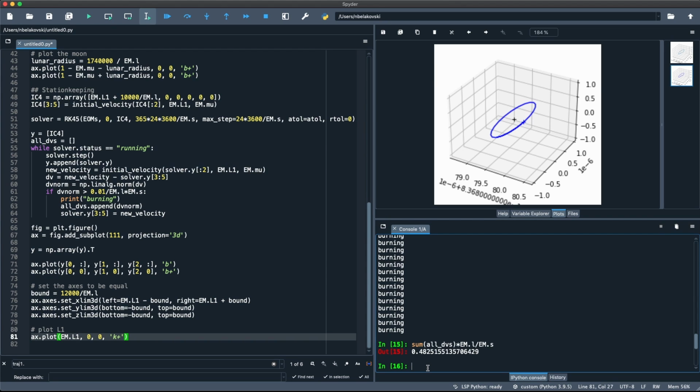The moon's orbit is eccentric, so you're going around in your orbit, and by the time you need to do a new burn, the Lagrange point has moved. And so you can recircularize, essentially create a new circular restricted three-body problem and figure out where your Lagrange point is and where you are relative to it and what your velocity needs to be on a circular orbit around that Lagrange point. But when you do this constantly, you basically are just constantly trying to find some Lagrange point to be near.